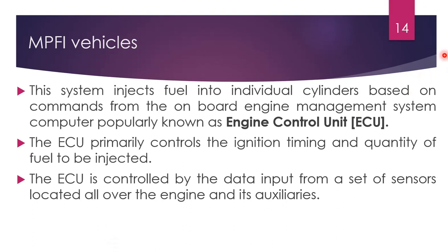So like common rail direct injection system, the MPFI system also has an engine control unit or electronic control unit, which is known as ECU, in order to control the opening and closing of the injectors. Okay, and the ECU primarily controls the ignition timing and quantity of fuel to be injected.